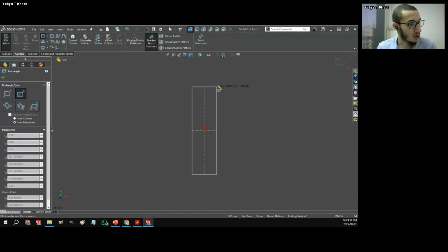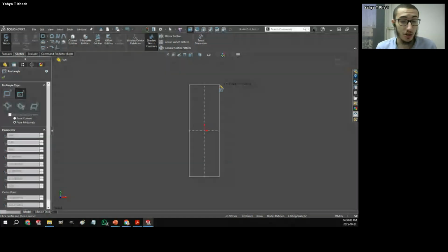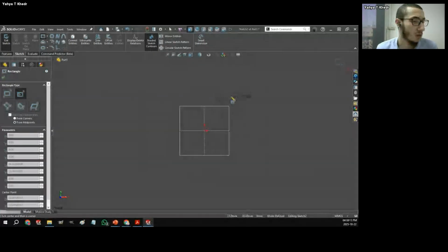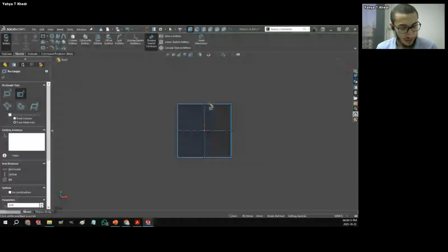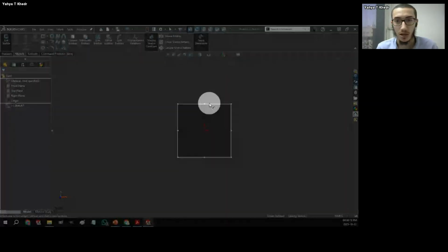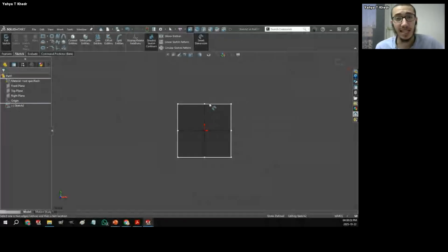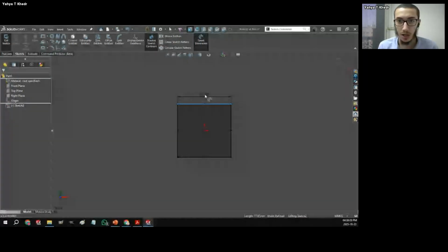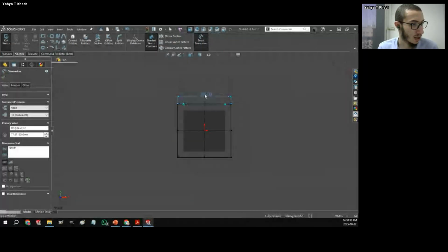Okay, so I'm using SOLIDWORKS 2025, the latest edition. And there's a very neat enhancement here: if I want to create a square with an equal relation between both edges, I can simply hit Shift on my keyboard, and as you can see, it's already a square. Then the Smart Dimension tool, I also have another keyboard shortcut for that. As you can see, the icon next to the cursor has switched to Smart Dimension without me having to move and select it. I can now enter the dimension, so it was 100 by 100. Okay, let me just make sure that I've got that.